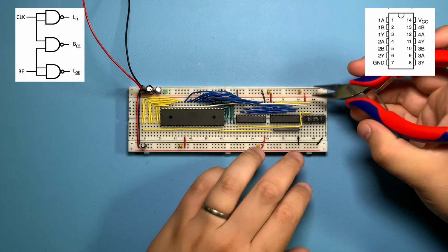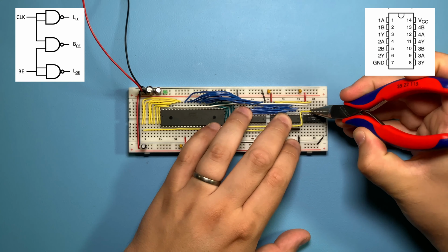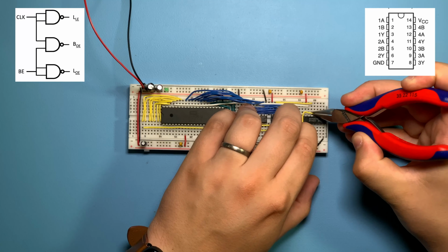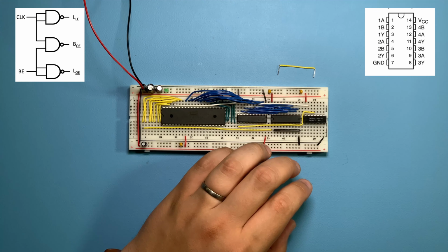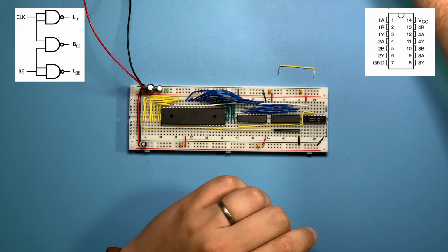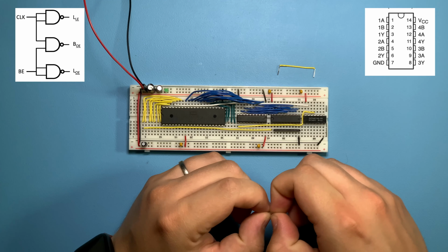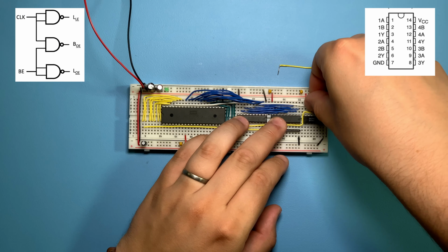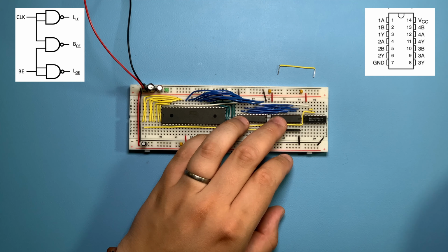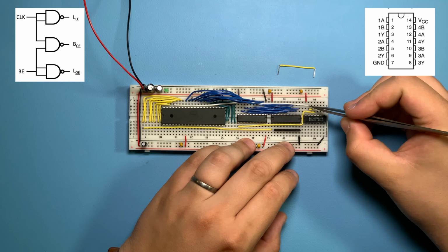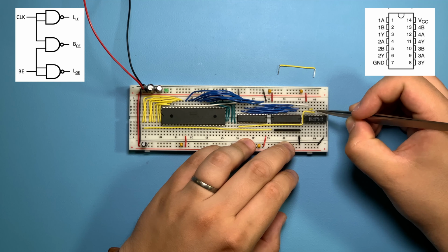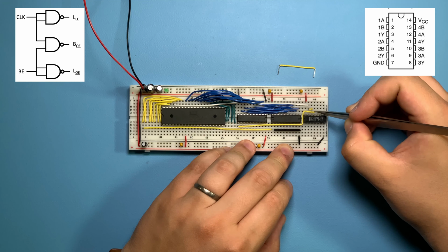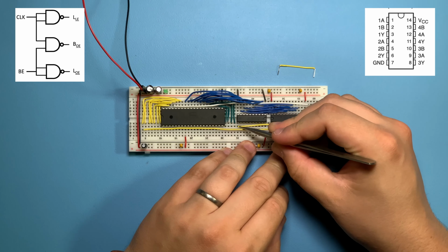So we need to bring this line over one pin. Luckily, it still kind of fits. And we're going to jump over the clock here. So this is the clock coming in. We put it into the 2 inputs of the NAND gate, and so that's the inverted clock. So it can go to the latch enable just before.